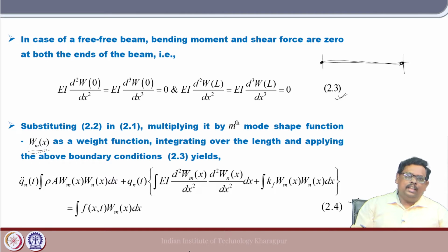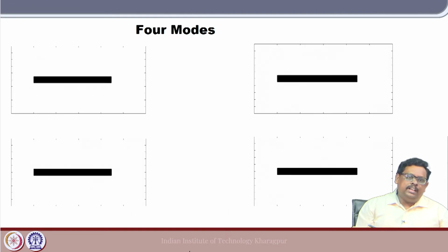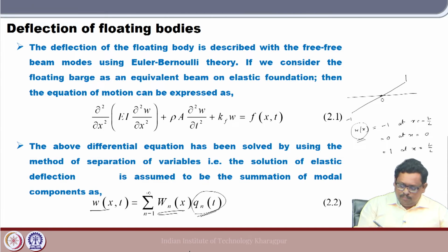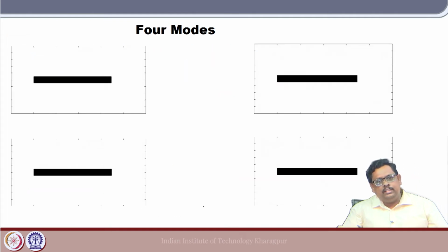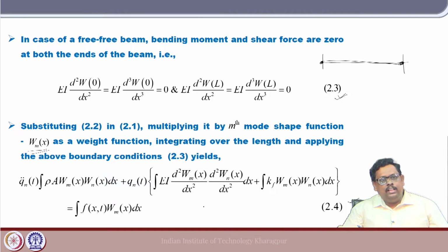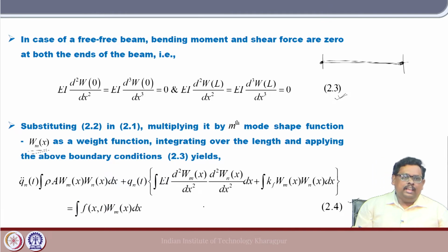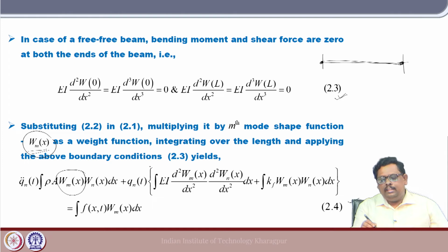We assume a particular mode which is Wn, then I write this expression, substitute this Wn into this differential equation, and multiply by another arbitrary mode shape Wm(x). Then I use the boundary condition and integrate from 0 to L.